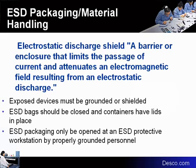The electrostatic shield is what gives a protection from any discharge. When the item is placed inside a metallized bag and the bag is closed and sealed, the operator can then disconnect from the wrist strap, carry it, transport it, place it in inventory, or move it to its next task. But before the bag is opened, it should be at an ESD protected area. The operator would have a wrist strap. As soon as they touch the bag, any charge on the outside of the bag would be brought down to 0 voltage and would be safe to remove the device.